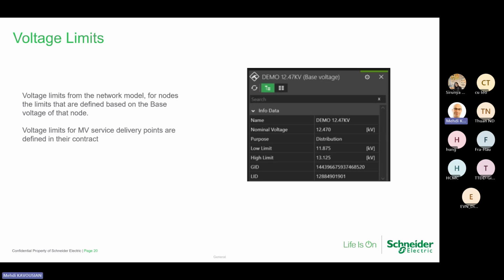Voltage limits for lines and transformers is the one that I was showing. For voltage, it's not per element, it's per system. But you can say for this 12 kilovolts, your measuring voltage 22, whatever it is, you can define for that voltage level. It's 5% higher, and it's actually very high. Two levels up, two levels down.